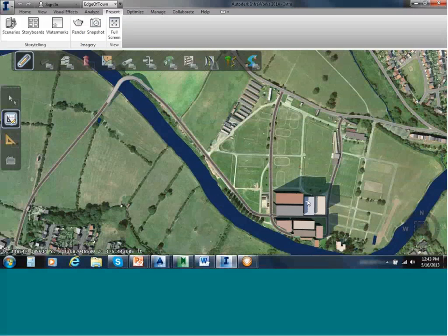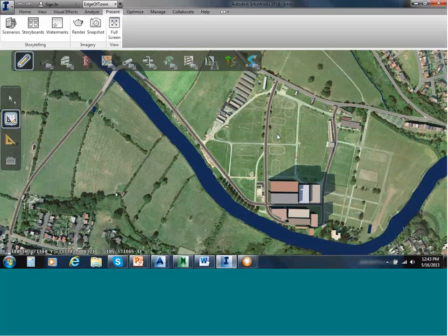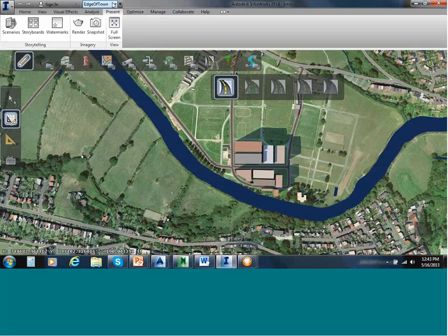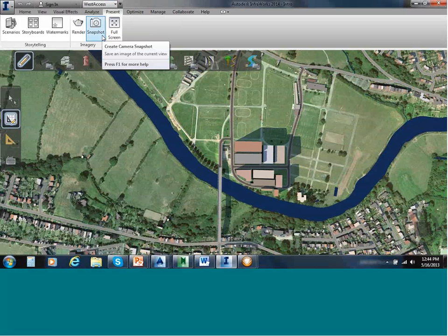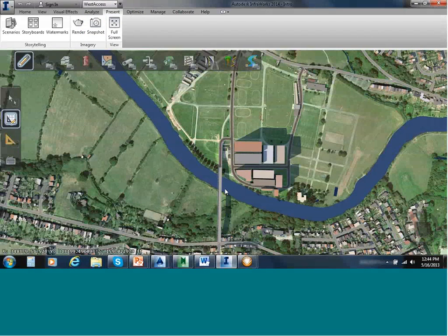And so if I were to actually go into InfraWorks, find it here, I have so many applications open. There we go. You would actually see I have all 3 of those models that I was talking about. I've got my edge of town option, I've got my east access, my west access, and when I choose a different proposal, you'll notice I'm in the same model, but it gives me different options. And we talk about how to take advantage of proposals in the model and switch back and forth so that we can truly analyze what's going on and how to work with that.